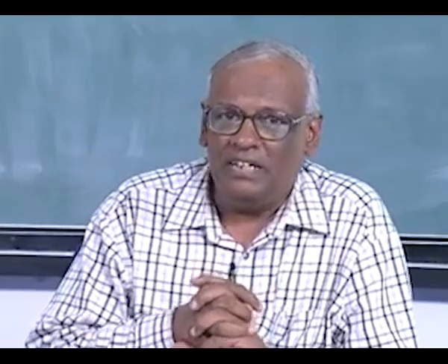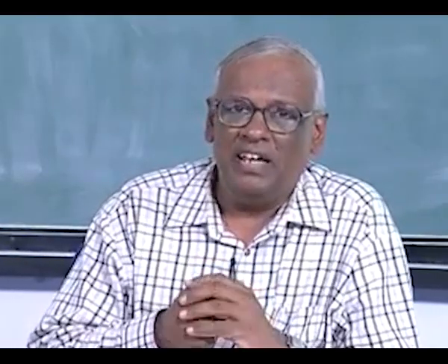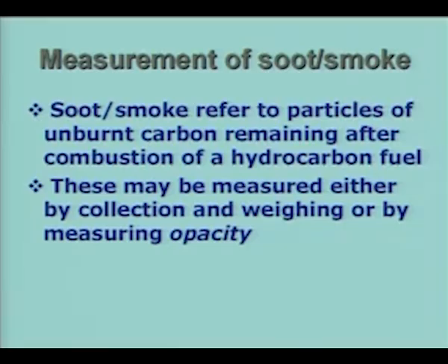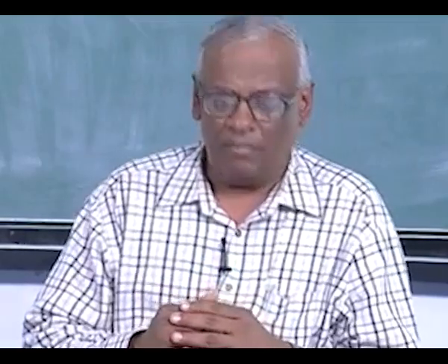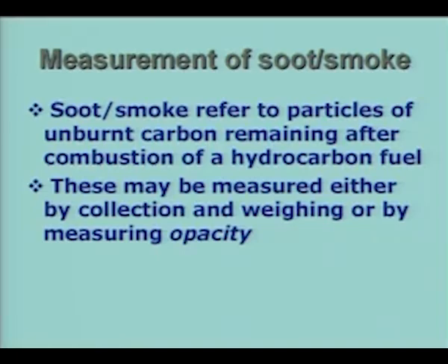The other method is to measure what is called opacity, and this can be measured in situ, that is, you do not have to collect a sample. For example, in the case of a smoke stack, the opacity meter can be mounted on the stack itself, so that the measurement can be done directly in situ.